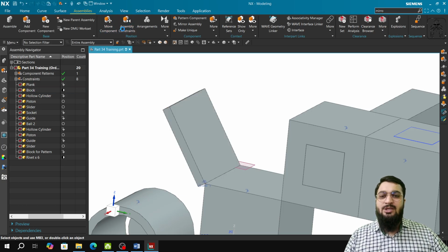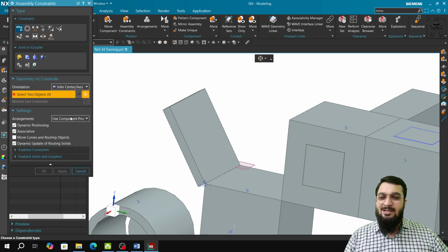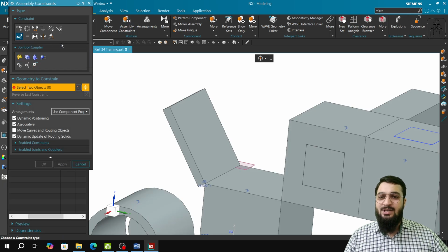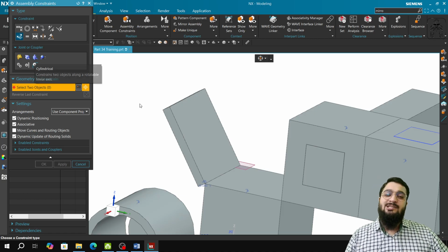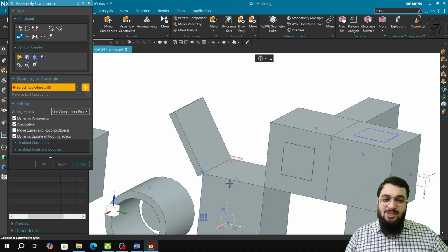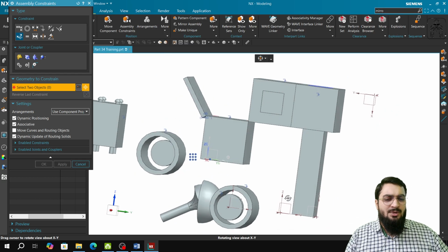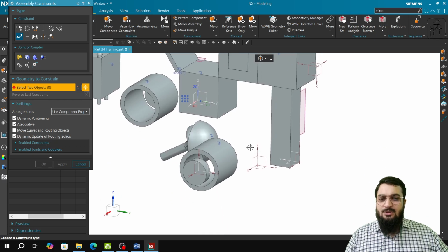Now coming to the next constraint, that is the slider. So slider constraint, you should not get confused. Slider constraint, cylindrical constraint, and the infer and center axis constraint, the align constraint, align lock constraint, give you the same result whatsoever. Only the thing is that the components with which it can be used with much ease are the thing of difference, but you can use them nevertheless. Okay, so now let us start.